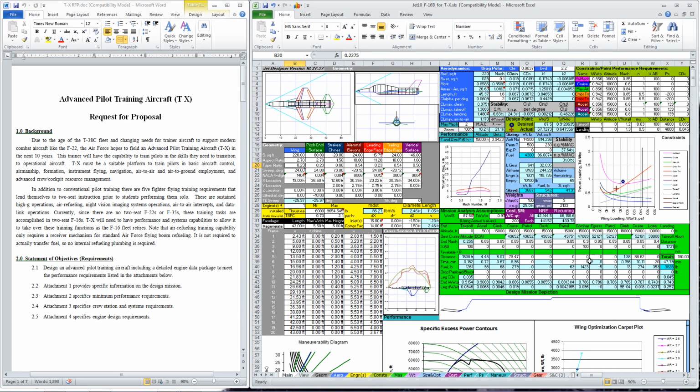Okay, and looks to me like we're not making the max Mach requirement at all now with that 2.7. So part of the reason though is probably because our wing's too big again. So let's try 200. And let's see, the airplane weighs too much.